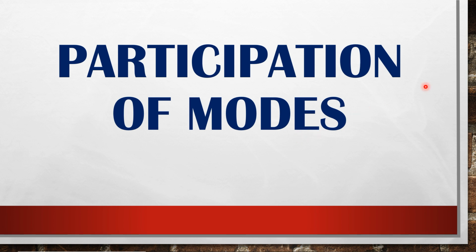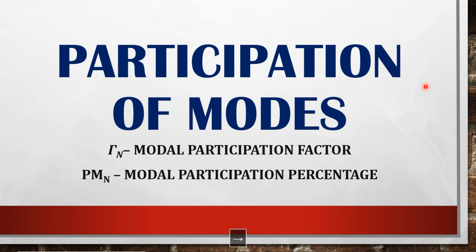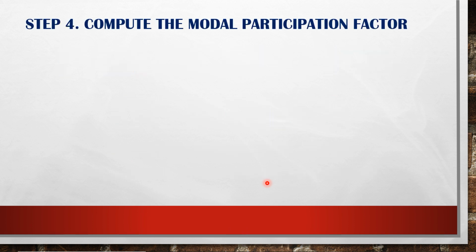So we will be solving two unknowns here, the modal participation factor and the modal participation percentage. Modal participation factor represented by the uppercase gamma n, and the modal participation percentage represented by PM n. So, step 4, compute the modal participation factor.